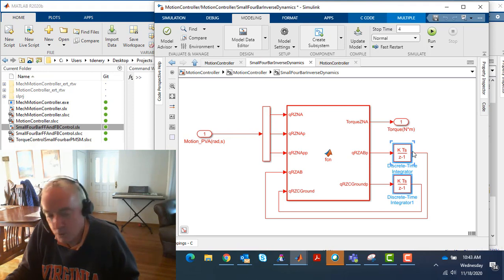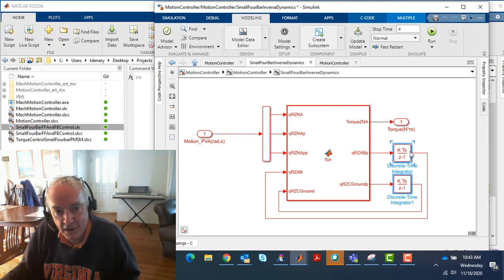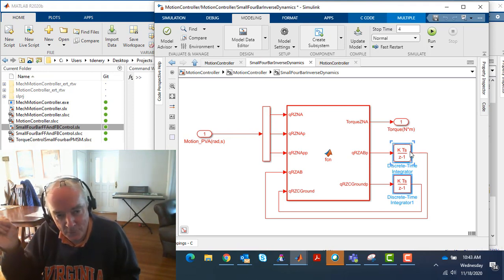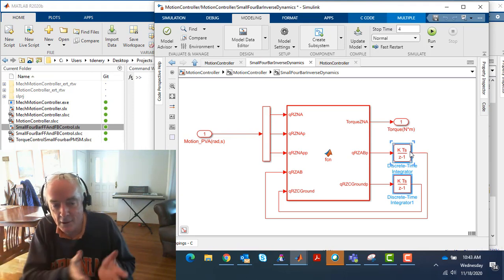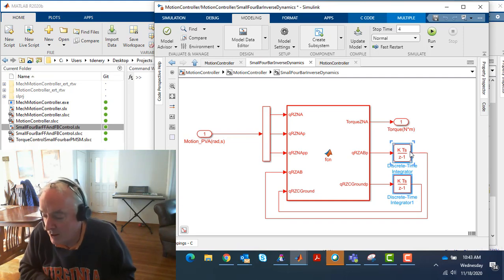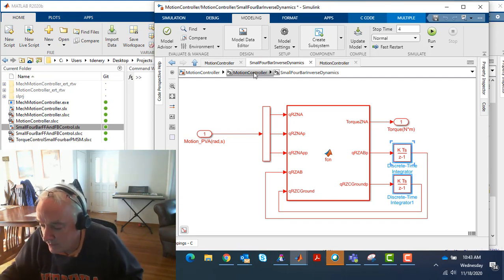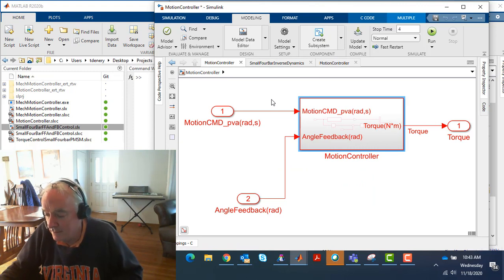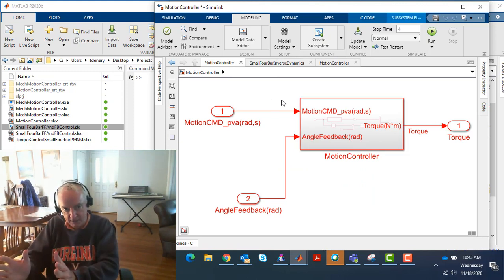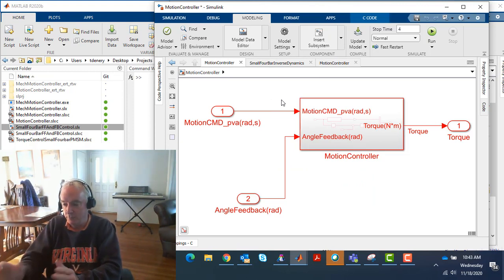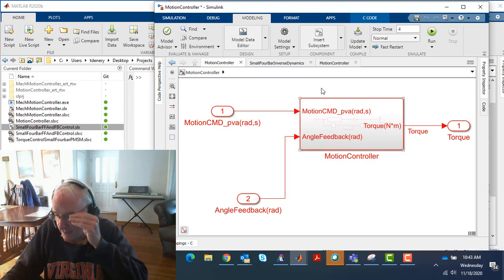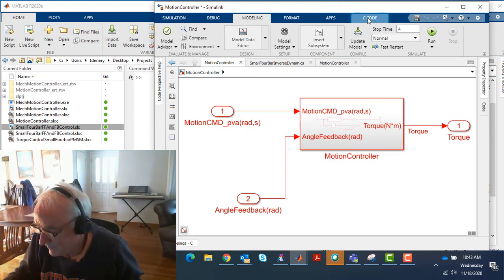These, I think, are forward Euler, and essentially it means I know what the derivatives are. I multiply them by my fixed time step delta t, and I update our previous value for those signals by that product. All right. So anyways, hopefully I've made my point that the math is fully contained and it's reasonably simple. And that's always a good thing for controls.